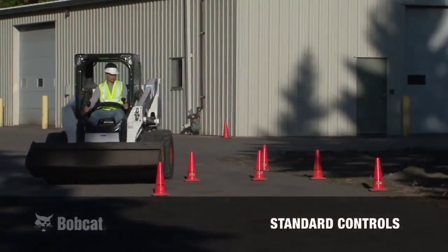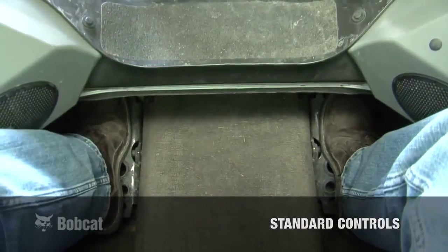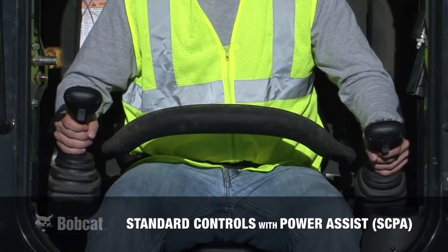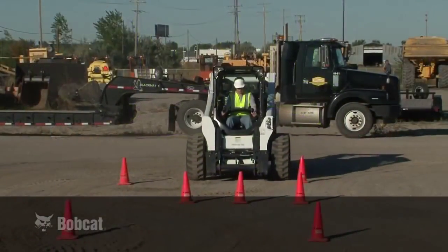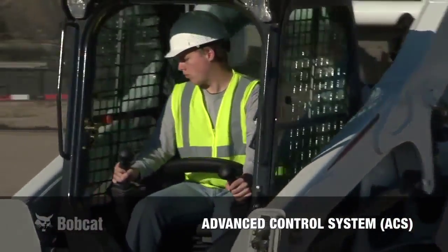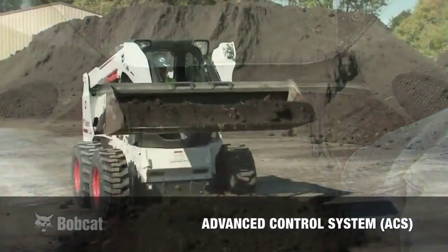Loaders equipped with standard controls provide steering levers to control drive and steering functions, and foot pedals to operate lift and tilt functions. Standard controls with power assist, or SCPA, function much like a standard control machine with power assist handles for drive and steering functions. Loaders equipped with the Advanced Control System, or ACS, provide steering levers to control drive and steering functions. The operator can choose between handles or foot pedals to control lift and tilt functions.